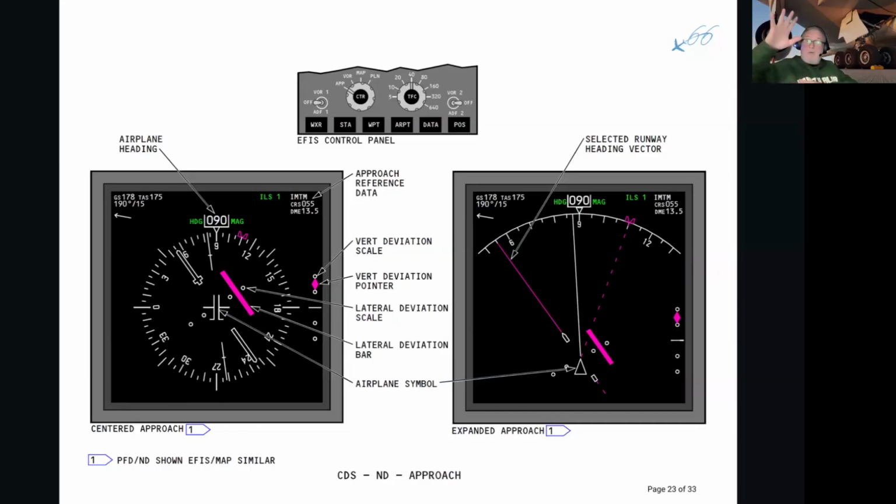And it will give him a vertical and a lateral flight plan, which the autopilot will then follow once the autopilot is engaged. Until the autopilot is engaged, the pilot will follow. But it's a long-term plan from takeoff up into climb, cruise, top of descent, and landing. So that's long-term. It's not short-term like up, down, left, right. Yes, we do go up, down, left, right. We do short-term navigation in between. We do have to climb, and we do have a top of descent.